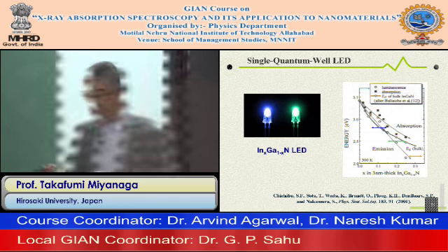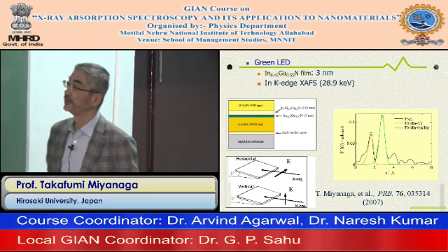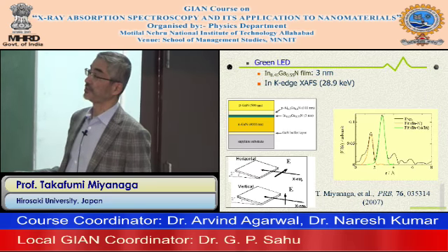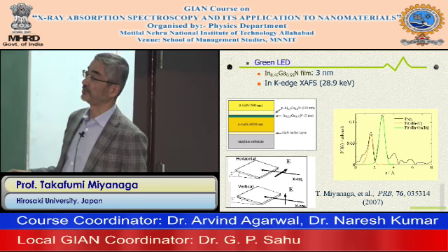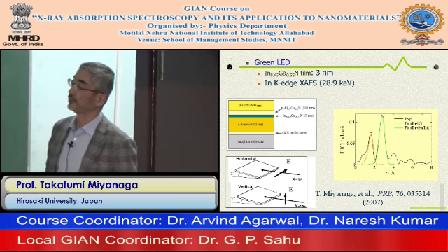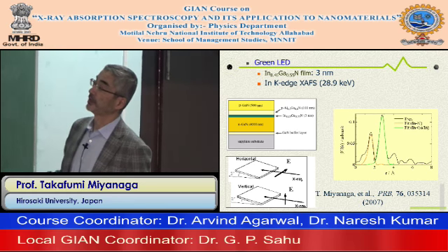So our sample is very thin, in extreme conditions. The substrate is here, the buffer layer is here, the active layer including the indium is just 3 nanometers, and the cap layer is here.